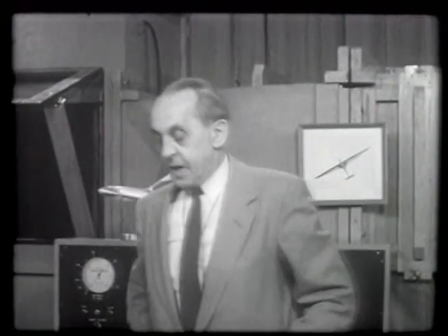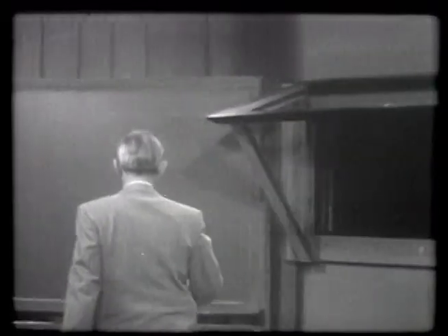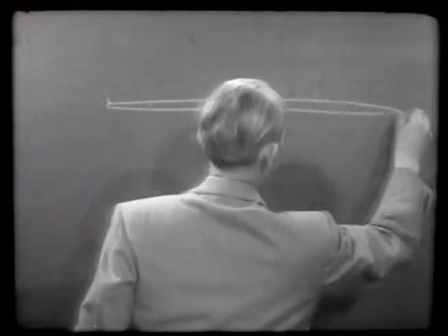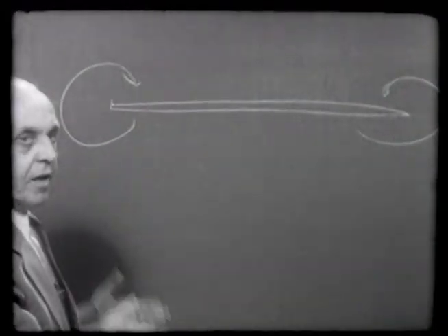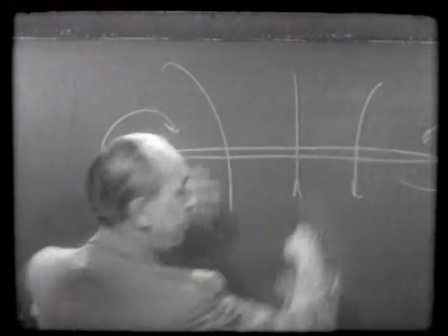Now, we might think how this vortex motion ties in with what we talked before, that the air is moving downward even at the point where the aircraft flies. You see, when we have here the wing and these vortices on both sides, they induce a downward motion behind the wing.